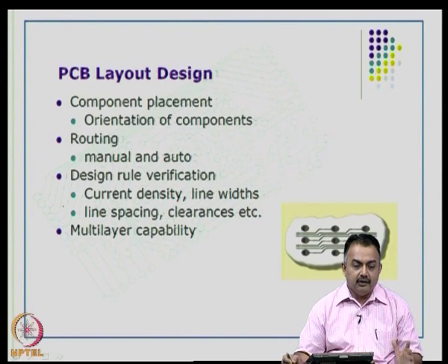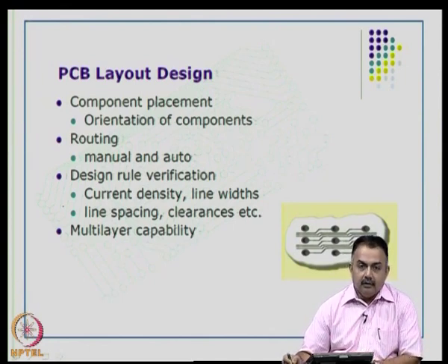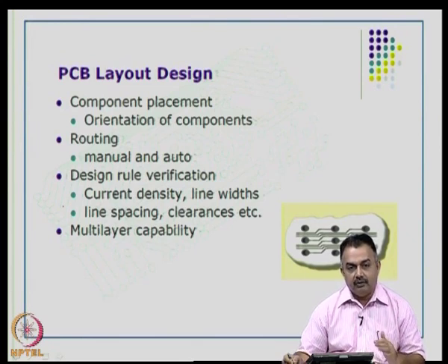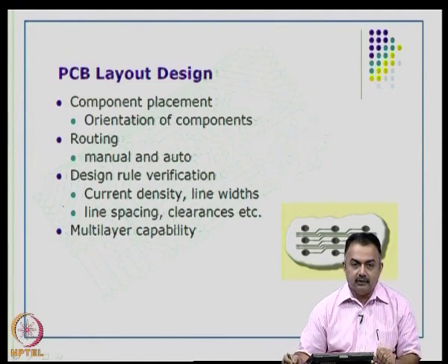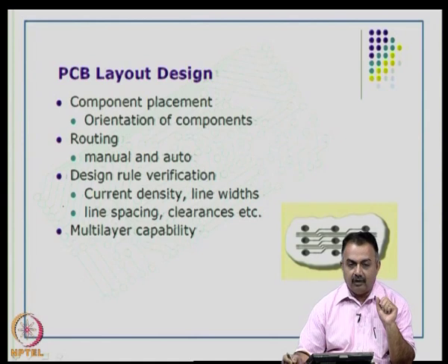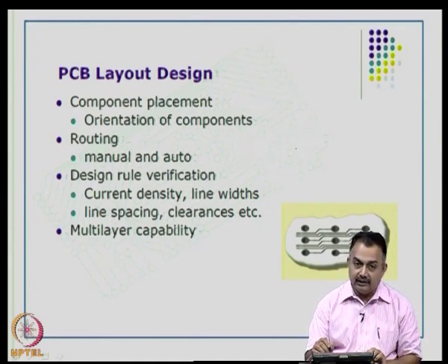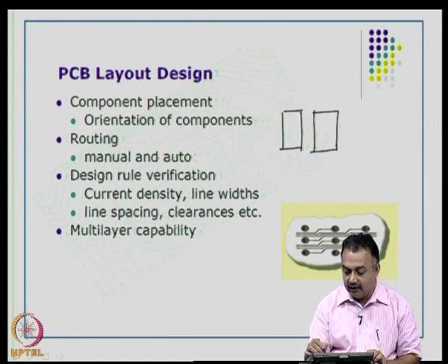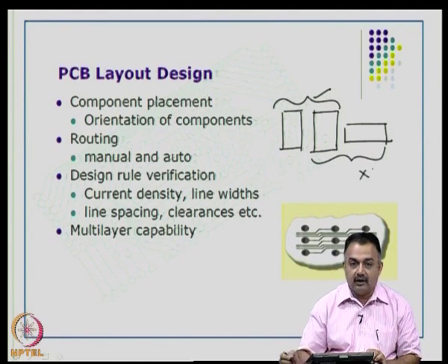Then the next module in any CADware will be PCB layout design, where you are working with component placement. In a given area which you determine as the PCB size, you have to place the entire set of components, both the actives, the passives, the electromechanical components and other parts, into that given space. So, the real estate here is expensive, and you have to make sure you utilize the CAD program to make a very good layout. The orientation of the components is also a key factor in achieving high density. For example, if you have two integrated circuits, you need to align them in the same orientation instead of having one like this and one in this direction. So, a combination like this is good, whereas a combination like this is not accepted.